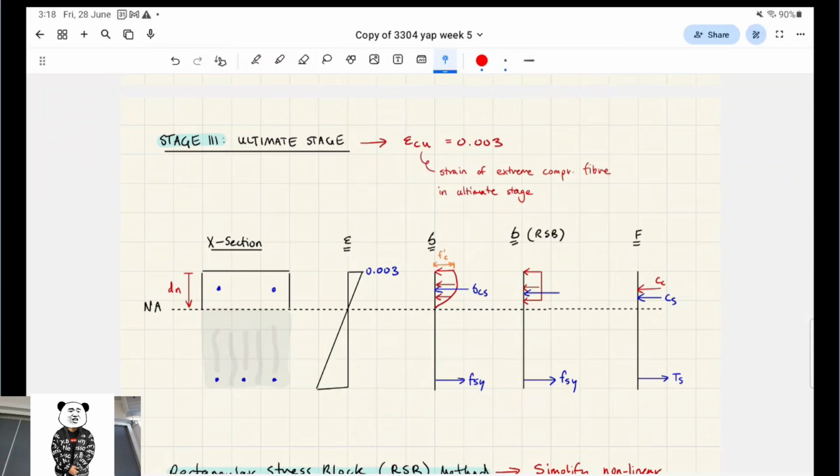Yeah, so you're right. On a material curve, let's just look at concrete, it'd be that point, yeah? The stress strain. But what defines that point? How do we consistently know that point? Okay, I'll give it away. That point is where the strain is equal to 0.003. That's the rule in the Australian standards, right?